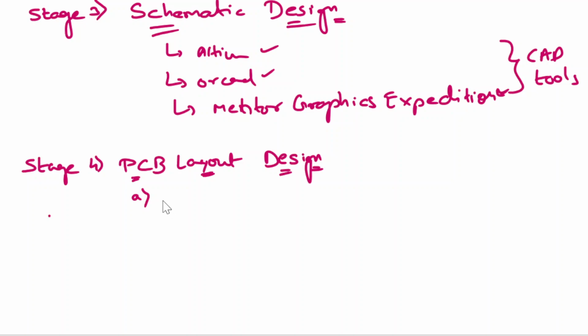So once we decide the number of layers, say for example 4 or 6, the dielectric thickness depends upon our design, or upon the PCB layout engineer's design. We give the requirement specification for him, like components, and the trace length and width should be this much only. We draw this in the schematic diagram, and the dielectric thickness between the copper layers is decided by our end, the designer end, or it is in the PCB layout engineer's hands. It's the responsibility of a hardware design engineer.